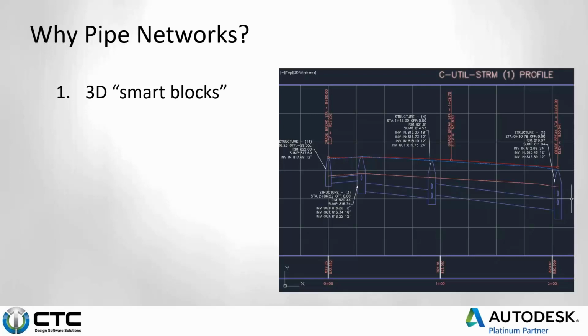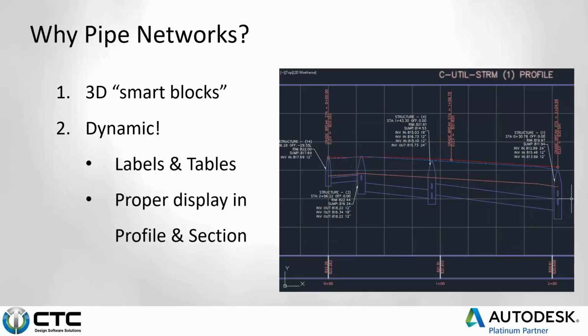All of this stuff gets defined to these individual, I don't want to call them smart blocks. And since they're Civil 3D objects, it means they're dynamic. So they automatically update our labels and our tables for us, and they properly display in profile and section views. So when we make a change to our design, we don't have to redraw the same ellipse 500 times for each one of our section views.